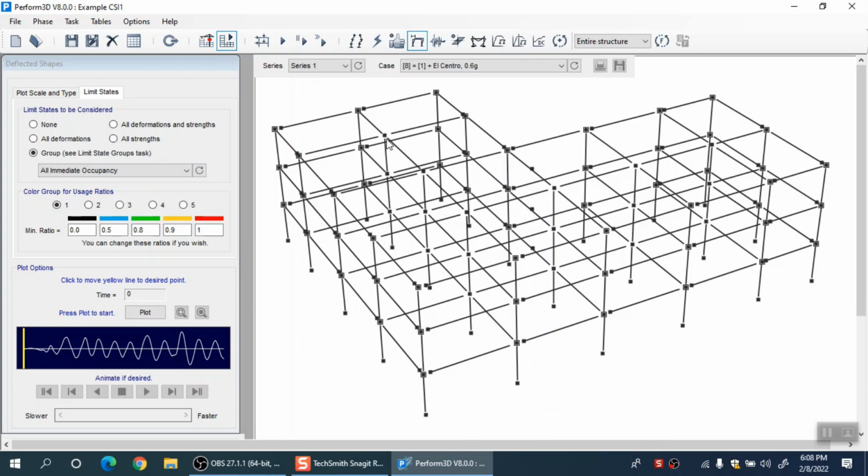So even if you model water with some solid element or with some more sophisticated modeling technique and ultimately you run static analysis, no inertial effects will be accounted. Similarly, if you run dynamic analysis but your computer model doesn't have those masses there which can represent inertia of water, again no inertial effects will be accounted, right.